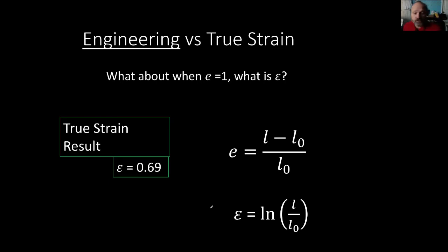So make sure you try it with a bunch of different numbers and be able to compare the two. This may be on a test, a quiz question, whatnot. So get an understanding of that. You can see the more you stretch something, the more strain you put a material under, the bigger the difference between engineering strain and true strain becomes.